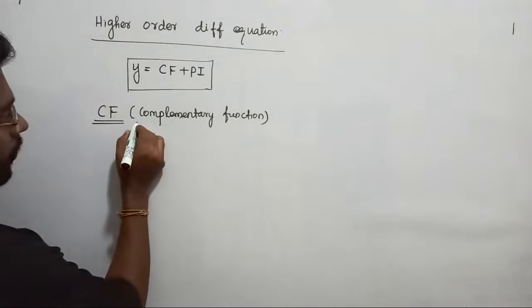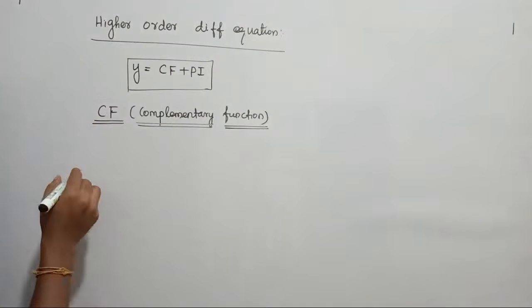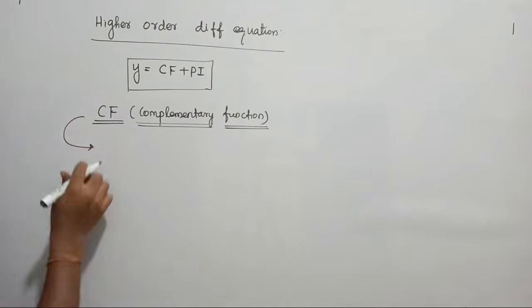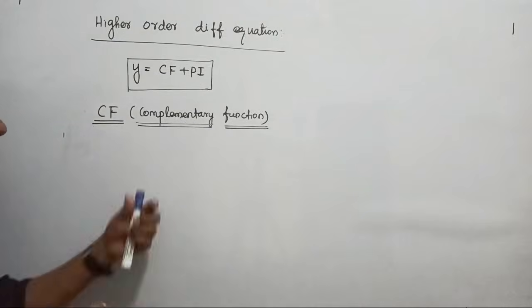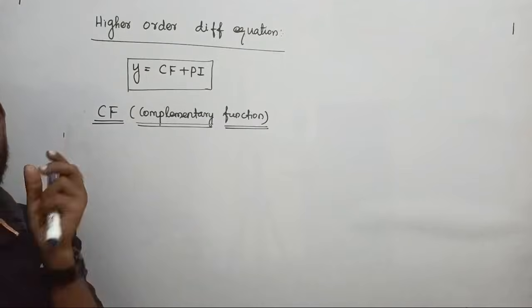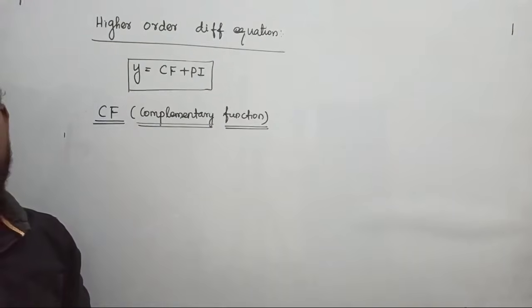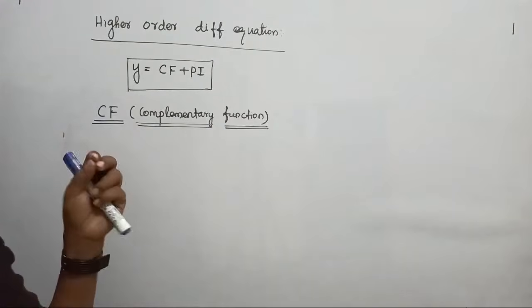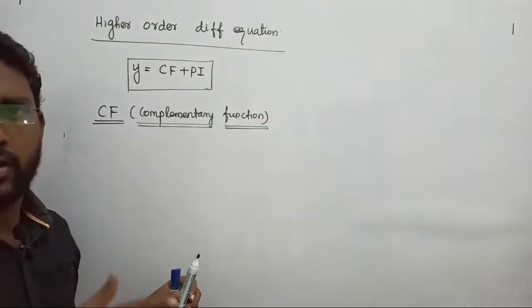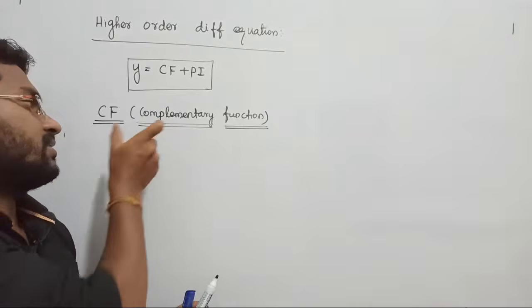Okay, so regarding the complementary function, that's very simple. First, there are four types of complementary function you can expect. It will just characterize the behavior of the system. If there is an inductor, what is the natural behavior of that inductor? For a capacitor, what is its natural behavior, how much time it takes in the system? When we are driving an inductor with the help of external supply, how long does its transient behavior last, and when does it die out? Clear? So that characteristic is what is characterized as the complementary function.